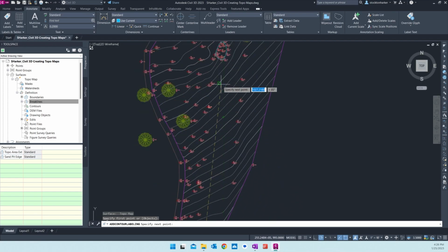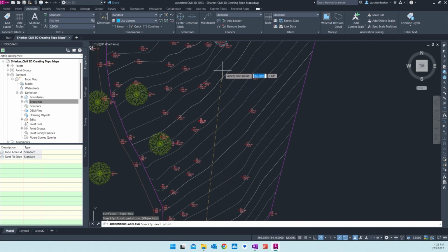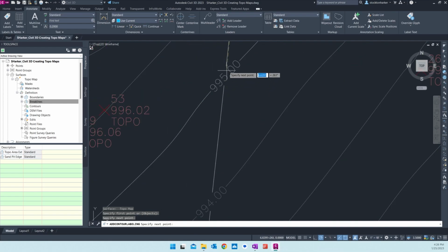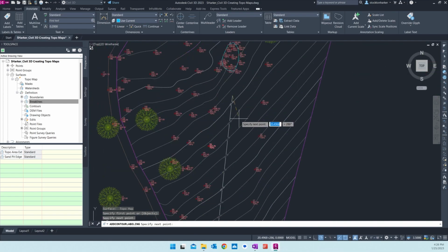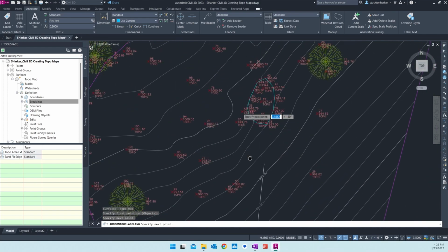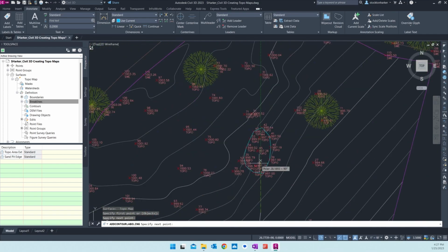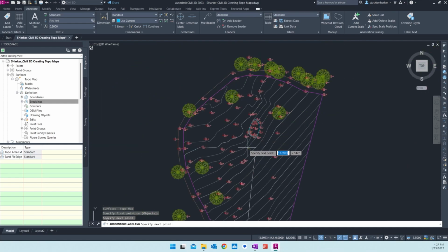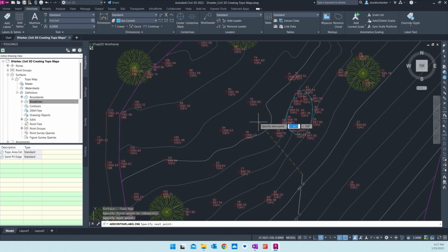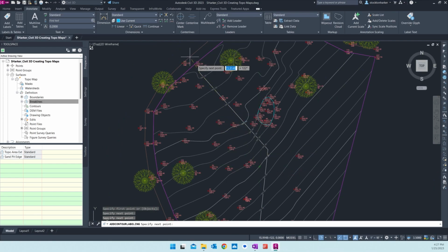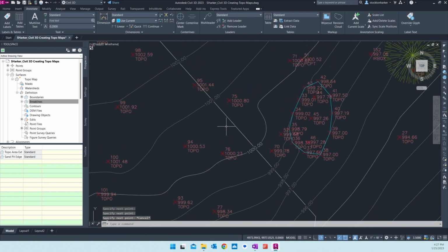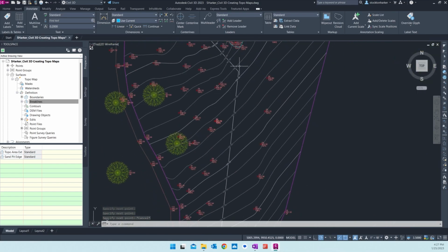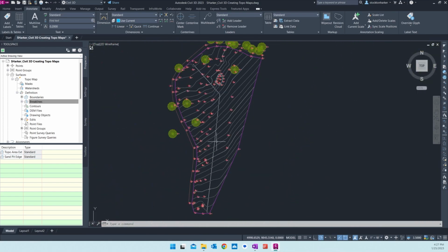We'll take the dotted line and drag it to where we want to go, and then click, and see it added some contour labels here. Where I clicked, it'll add a vertex, so we can go a different direction, because I would end up going straight through the sandpit and that one looks so good. So now we can come over in this direction, and when I've got all the contour lines that I want to label, I can hit X. Fantastic. Now I can see very clearly what the elevation is of each of these contour lines.